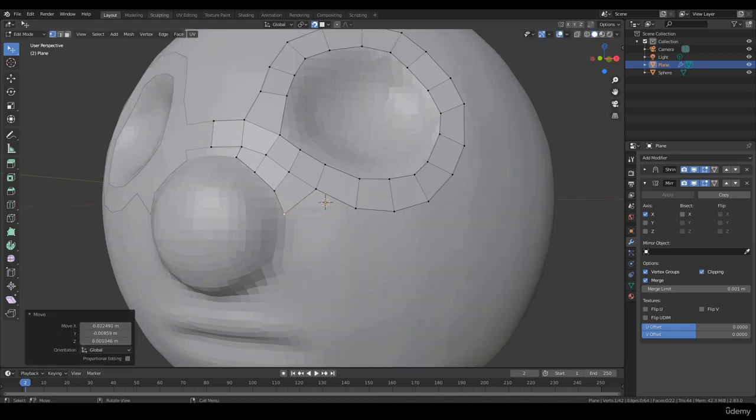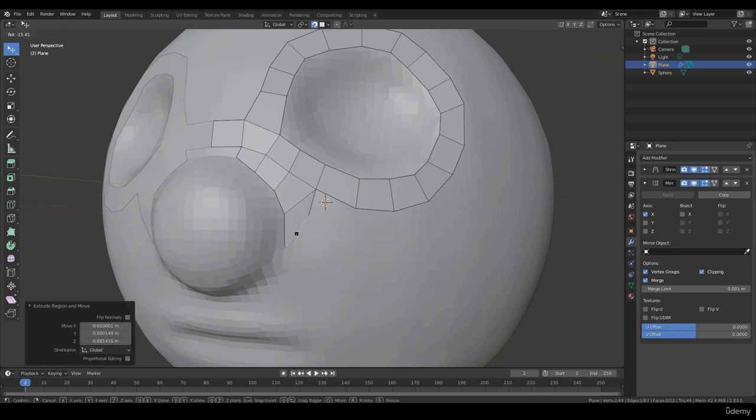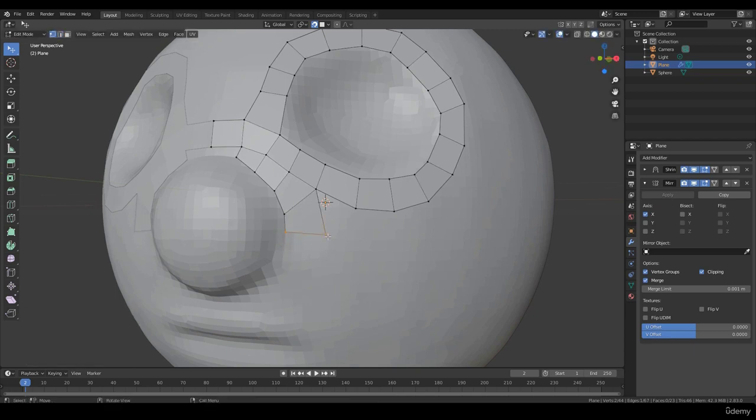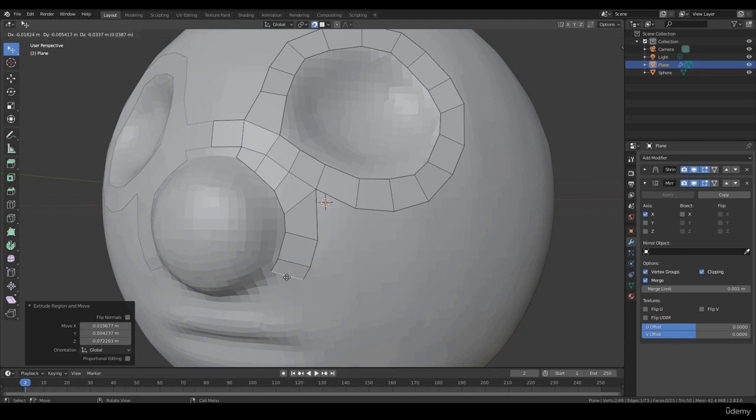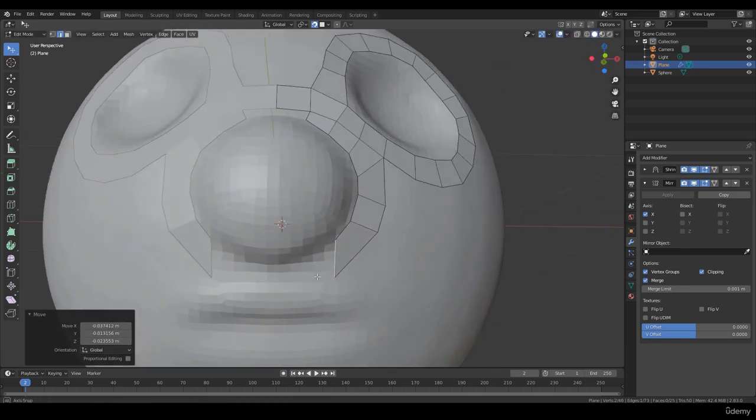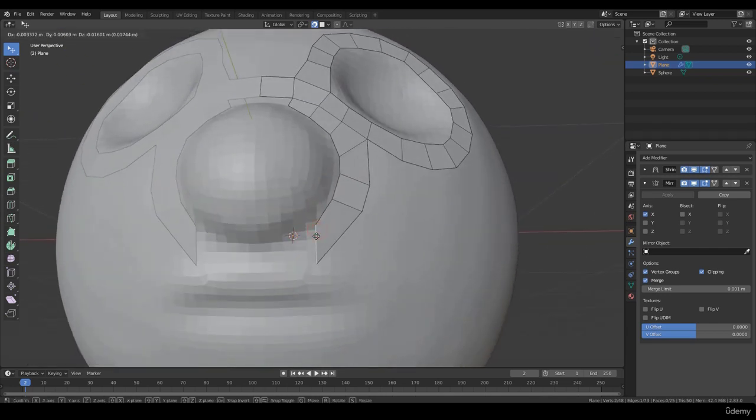And I can go to my edge tool again, select this edge, press E, R to rotate, and G to move. Press 1 for the vertex. And I can go here, press E again, press R to rotate, press G to move. Okay. And I can hold Control and right click, and there you go. And I just have this meet up in the middle.